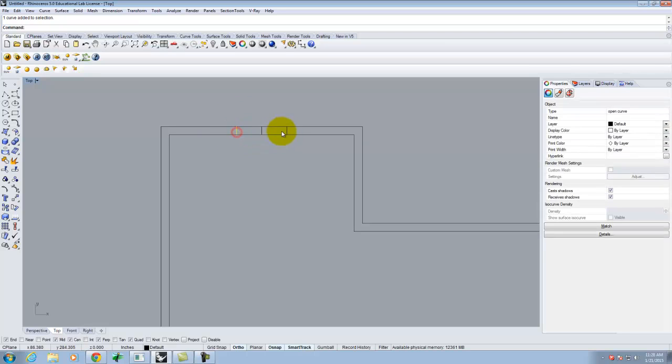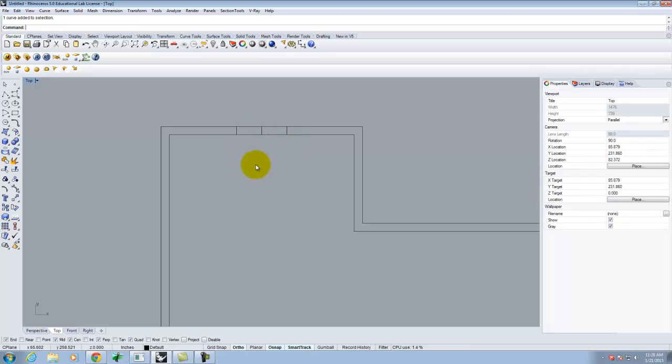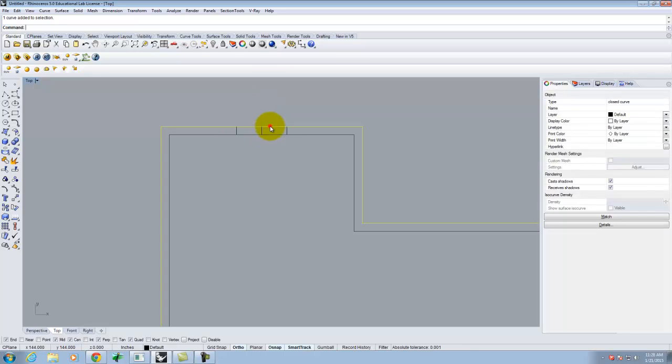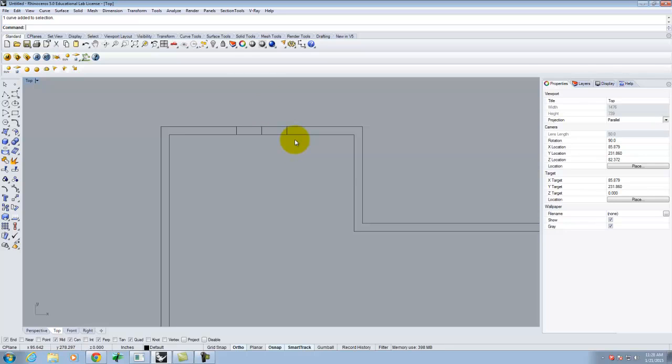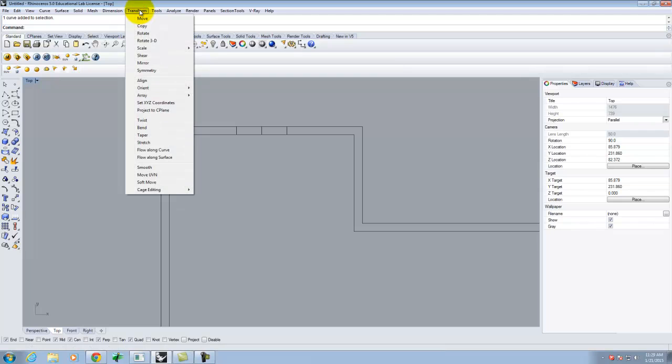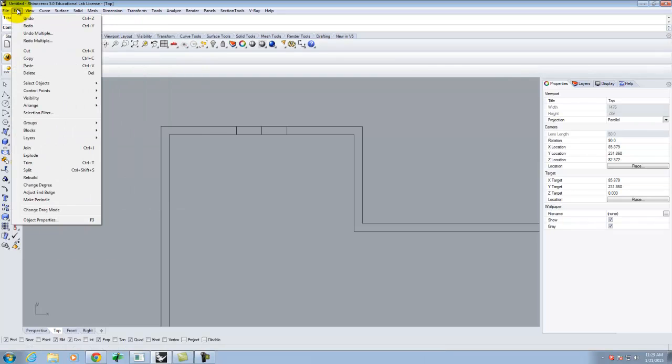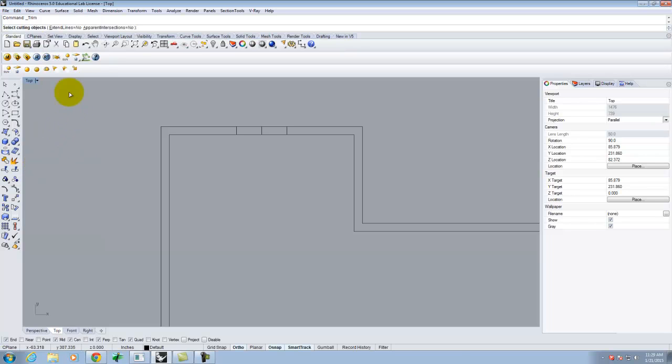So I have 2 lines here and here, and because this is a doorway, I actually want to cut these 2 larger lines out, right, and remove them. So I'm going to use something called trim to do that. Okay, and this is one of the easiest things to use because it's a great way of clipping off ends of lines. If you've ever worked in AutoCAD, I'm sure you've done trim before. Okay, so trim is under transform, I think. Never mind, it's under edit, trim. There it is. I almost always type trim, right?